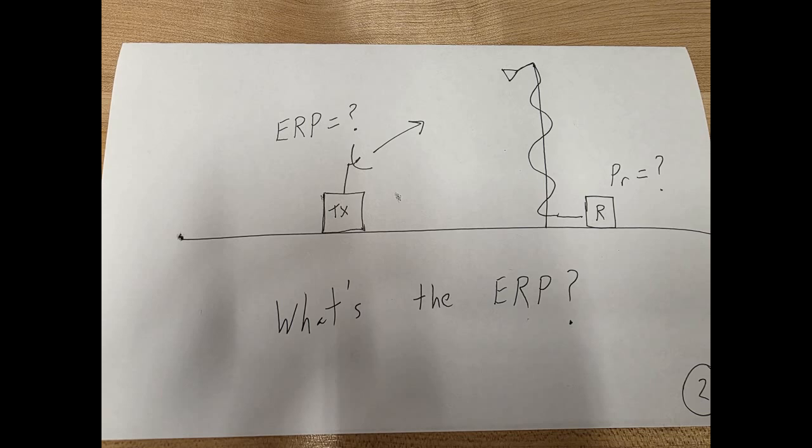You measure that received power, and then you can compute what the loss is. And then you put your system under test in place. And since you know what the loss is, because the loss is going to stay the same, you can compute what the ERP is, which is just the power received plus 80 dB in this case.